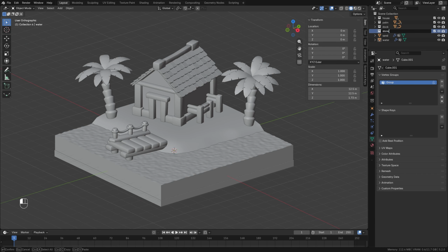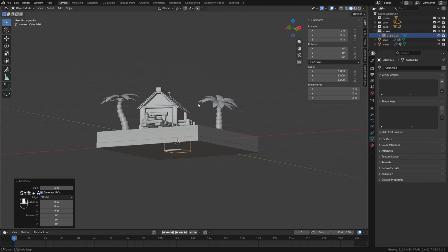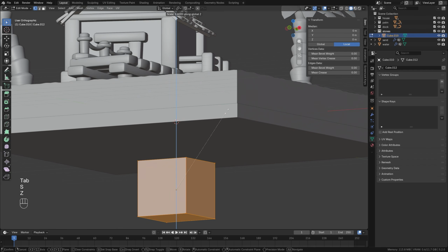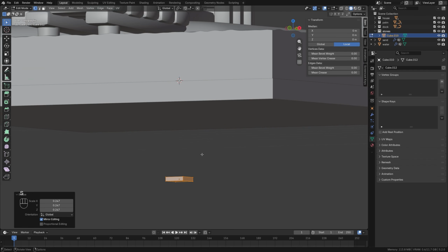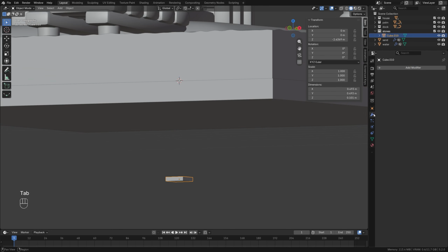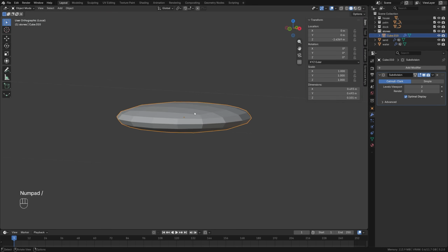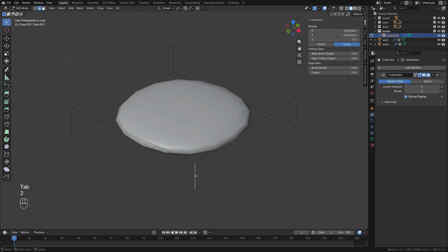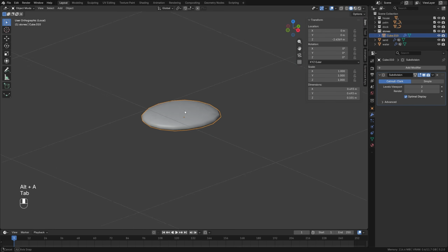We create a new collection, call it Stones. And first into this collection, we will create one small stone. This will be a cube. We will lower it down. Let's right away in Edit mode make it significantly smaller. We will assign for it the Subdivision Surface modifier to level 2. We will switch to its local view, right key, Shade Smooth, and also in Edit mode, select one edge and shift it a little to the side so that it didn't have an ideal shape.